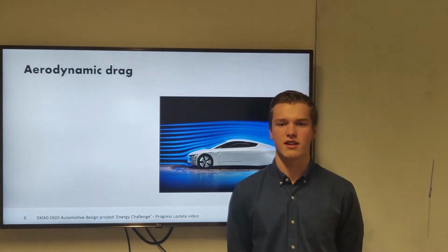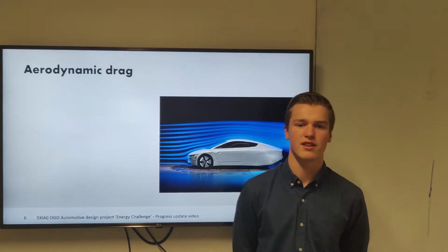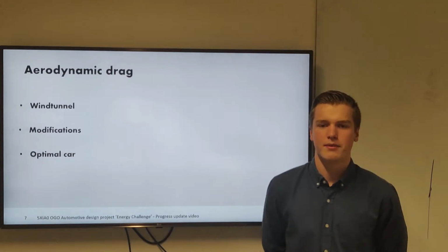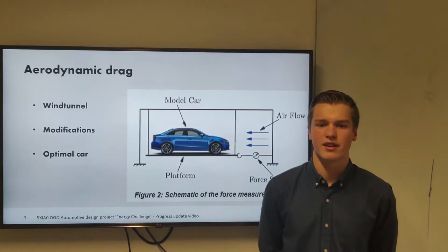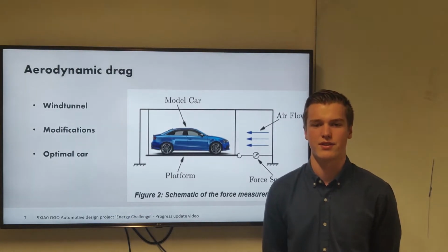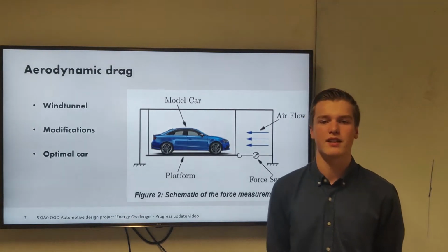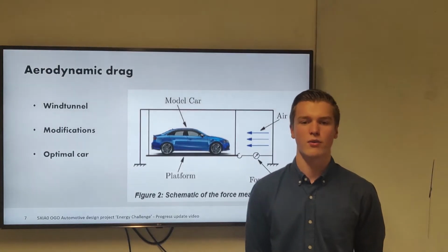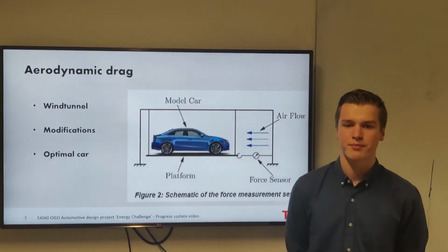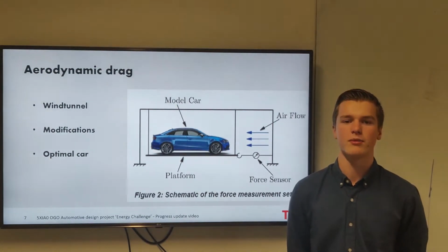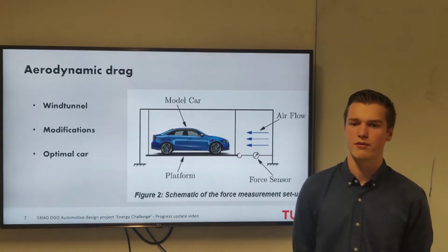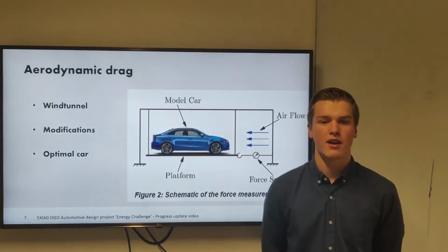During this test, the model car will be placed inside a wind tunnel on a hanging platform, so that the car does not experience any rolling resistance. A force sensor then connects the front of the platform with the wind tunnel such that the aerodynamic drag force can be measured. The experiment will be conducted at a number of constant wind speeds,